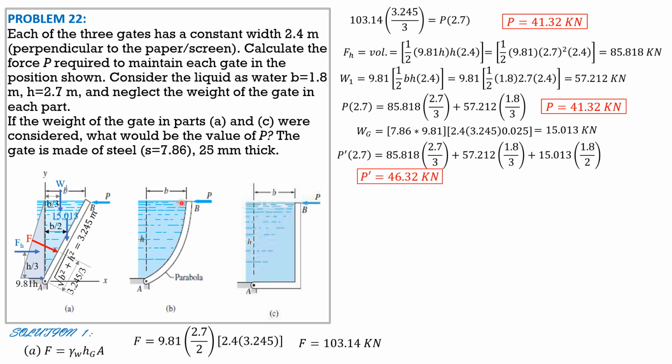principle. Since the tangent at A is inclined, as shown, and the tangent at B is vertical, or if you flip or rotate the figure, the tangent at B is horizontal, therefore this is the location of the vertex, and it is an open-to-the-left parabola. So the centroid is 2/5, because from here to the centroid is 3/5 of B, so 2/5 of B, for the weight of water inside this parabolic arc.